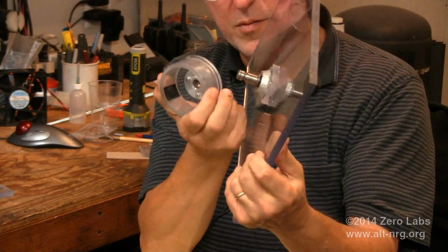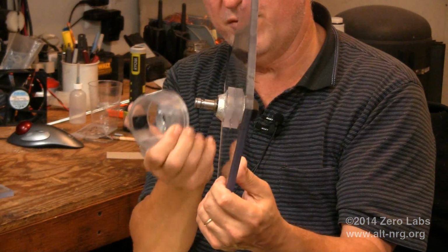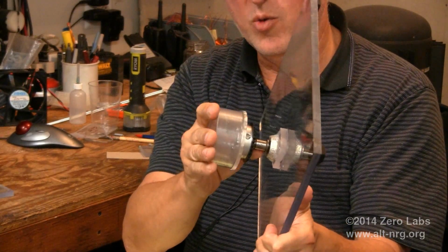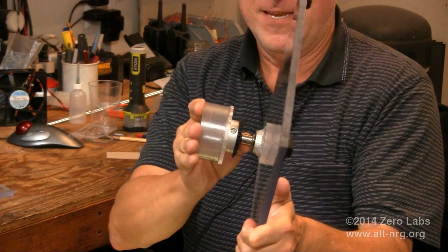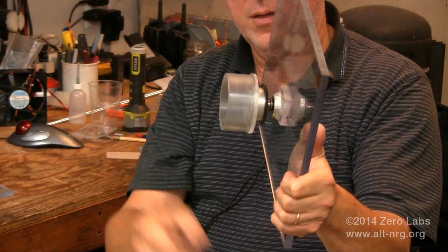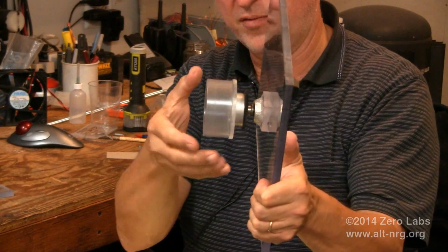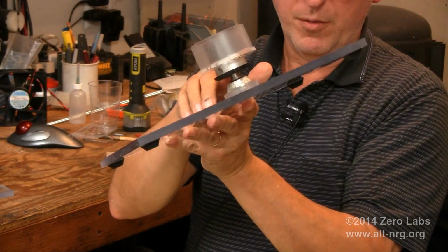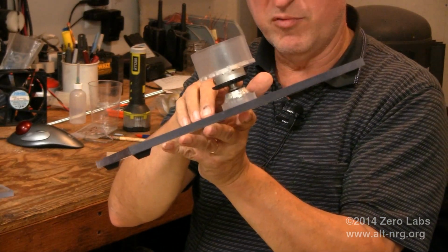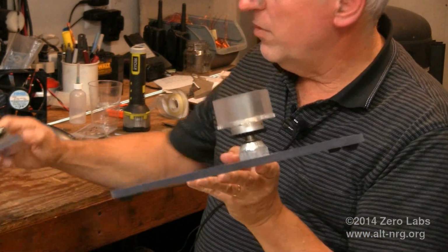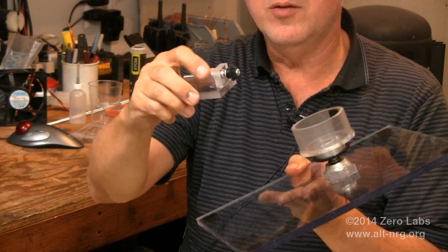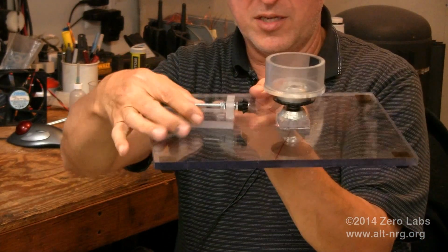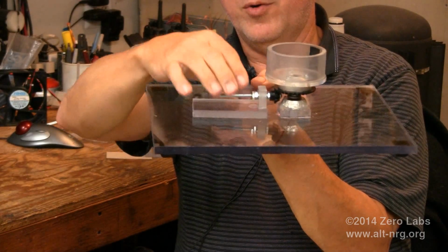I'm going to pop it off the spindle so that you can see how it pops off. The spindle rotates very freely, and there's just a spring-loaded ball bearing inside the opening of this aluminum hub that locks it into place on the bearing shaft. Now underneath is a bevel gear. It has 30 teeth on it. This was printed for me by Russ Grease. To go along with it, I have a pinion gear on a couple of bearings with a sliding acrylic frame that sits on the base of the motor.